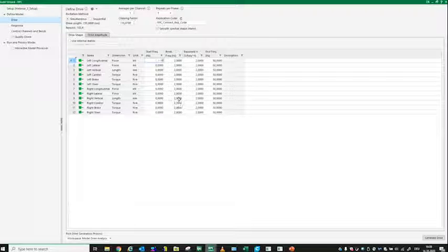Now I do this exactly the same as I did in Pro. So I type in a 5, and then hit enter. And what happens, it's a real-time validation check. It's telling me here's something wrong. The start frequency for left longitudinal is invalid. And of course, it might be the case that I just forgot to change the break frequency to a higher value. So it might be that this one is wrong as well. So it's checking both.